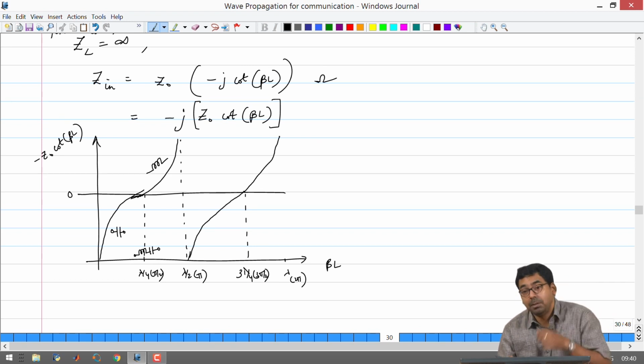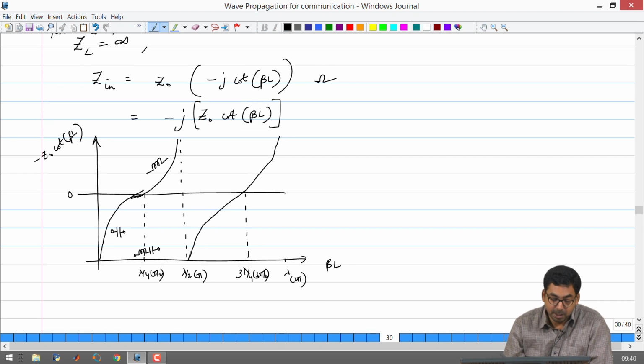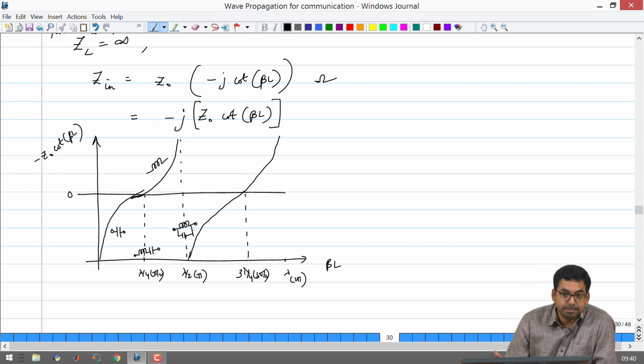Then we also have to talk about the equivalent circuit at the place of discontinuities, that is you are having plus infinity to minus infinity going in your y axis for the input impedance. In those cases, it will be a parallel combination of L and C. Okay.